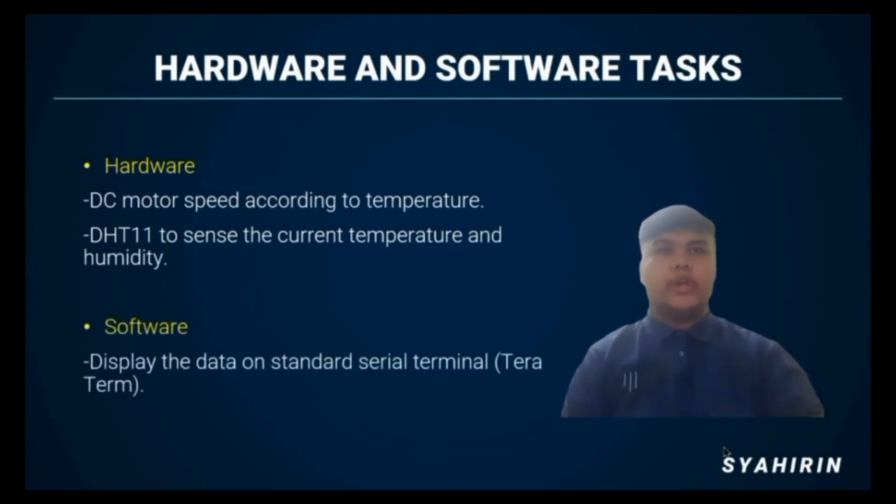Next, for the software, generally there is only one aspect to be considered, which is to display the data like the temperature and humidity, and also the checksum and the transmits pass. If it fails, it also needs to be displayed on the Tera Term. The Tera Term is the standard serial terminal that we use that will display the messages.